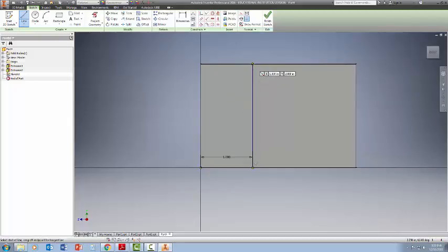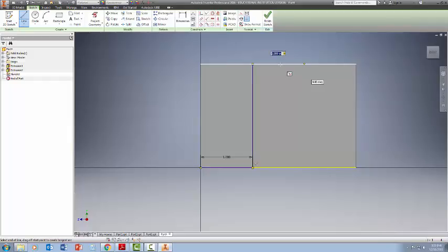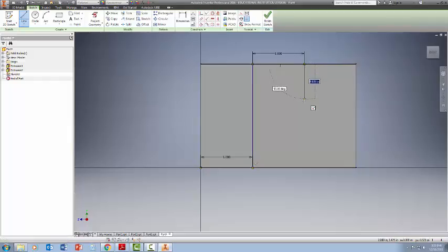Okay, now what I want to do is from this point here, I want to click, and bring it over how far? 1 inch. Type in 1, hit enter. I want to bring this part down. How far? I want to bring it down all the way to the bottom, but look, it's not completely 90 degrees, so I have to make it 90. It says 90, good, click.